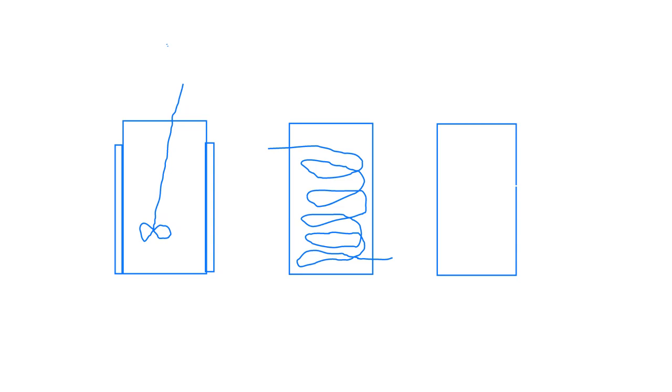And you can only have that much area of coil. Double coils don't work so well because you don't get such good mixing. If you've got a single mixer in here, double coils do not work as well. So yes, you do get a little bit better scaling of coils in a reactor than in this one.